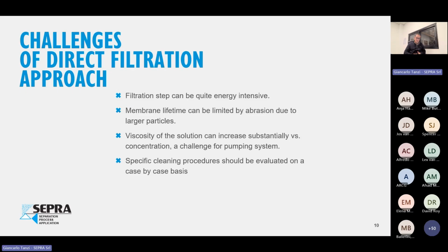We have seen some cases, very extreme membrane bioreactors, where maybe the prefiltration up front is not too good, but it's quite difficult to have abrasion because the suspended solid concentration may be very, very high, but we are always talking about flocs, about bacteria, about inconsistent solids. While here we are talking about particles, and above all, if you're not separating up front the bigger and most solid particles, you may face serious abrasion problems.